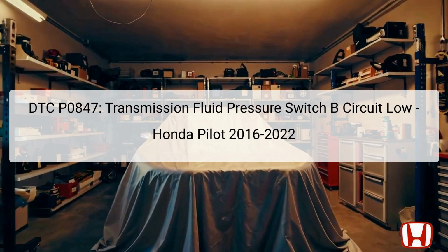The Diagnostic Trouble Code DTC P0847 indicates a fault within the transmission fluid pressure switch B circuit, specifically regarding the third clutch. This code is critical because it typically arises from an electrical issue rather than a mechanical malfunction within the transmission. When this error code is active, the transmission exhibits a fail-safe behavior, meaning it will only shift into third or sixth gear, limiting vehicle operation significantly and potentially leading to a safety risk.